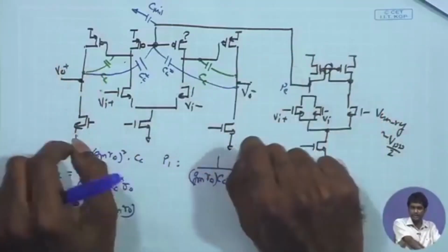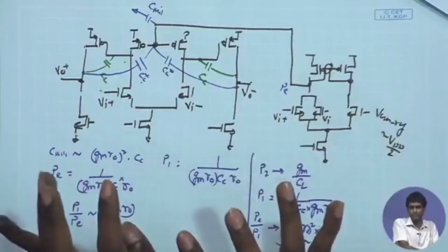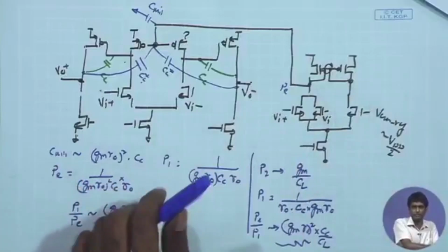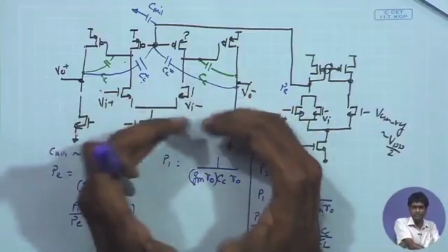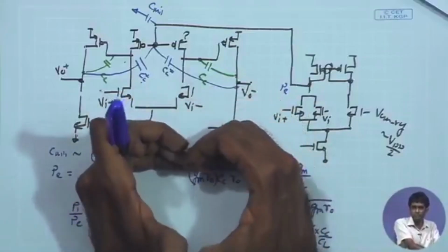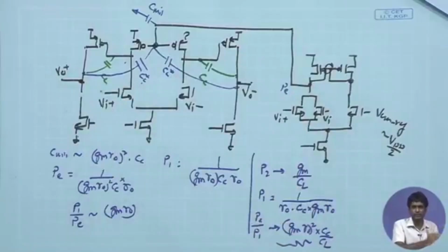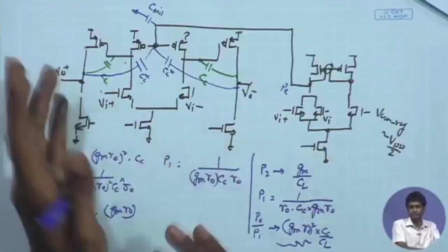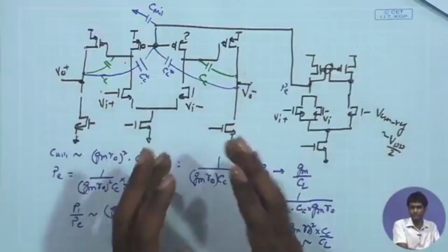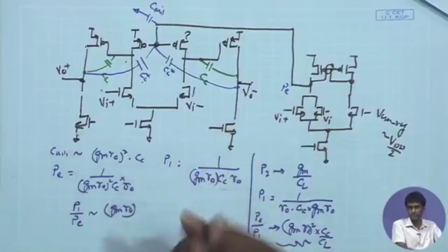So we will take one example where whatever analysis we have done for these different properties: noise, bandwidth, stability, input swing, common mode range, will be combined together, giving us some starting point for the device dimension and the component values, with which we can start the design, and then based on the simulation results we can fine tune the design in the right direction to get closer and closer to the spec, or get better and better in terms of optimization of various metrics like power consumption, noise and bandwidth, resolution, etc.